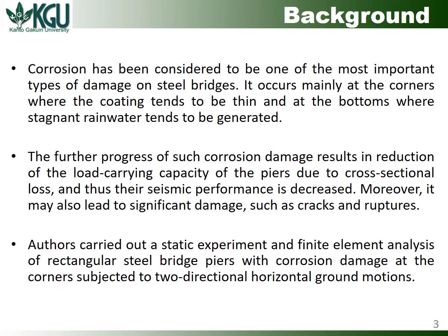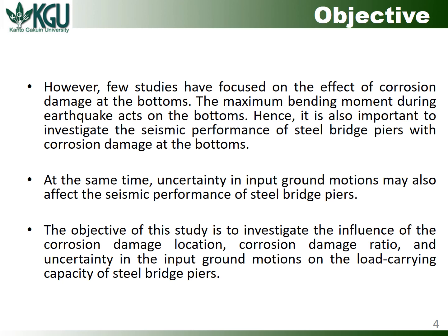As the previous study, we carried out a static experiment and finite element analysis of rectangular steel bridge piers with corrosion damages at the corners, subjected to two-dimensional horizontal ground motions. On the other hand, few studies have focused on the effect of corrosion damage at the bottoms. The maximum bending moment during earthquake acts on the bottoms. Hence, it is also important to investigate the seismic performance of steel bridge piers with corrosion damages at the bottoms.